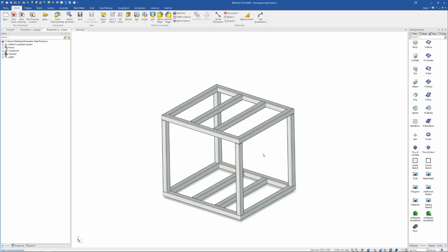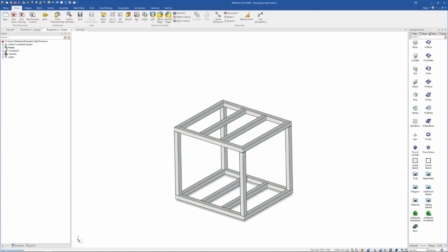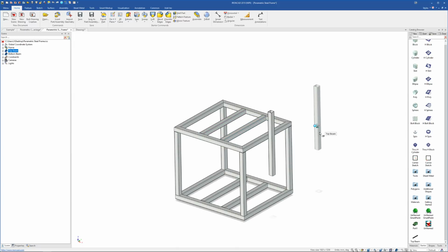So let's say we're just wanting to take a few parts out of here and copy them somewhere else, just save them to the catalog. Instead of having to select down to the part level, then try and select the other part, or that one's linked, or try and select this part, get to this one, hit the pattern, and so on, we can just change the selection filter over to part. And then when it's on part, the first click is going to be on the part. So just go straight to the part, no matter what. And it makes it much easier to then just select the parts we want. In this case, we're going to select both of those and we'll drag them into the catalog. So it's much easier. Then we'll select one. Obviously this one's the dual part, and the other one's the single part.